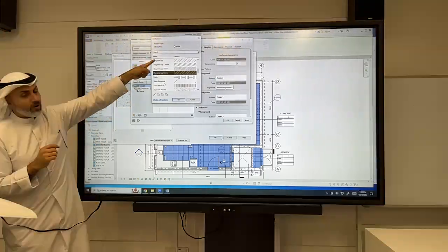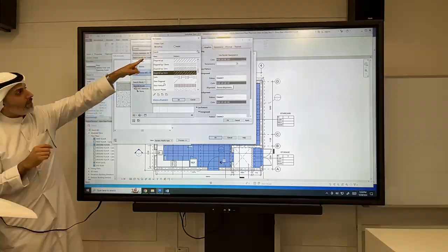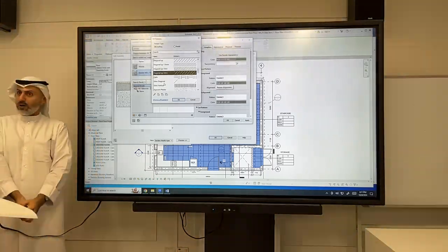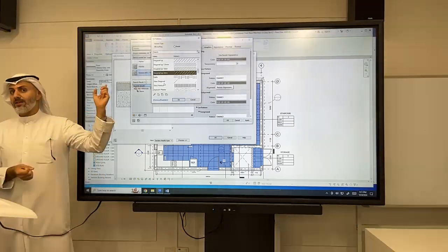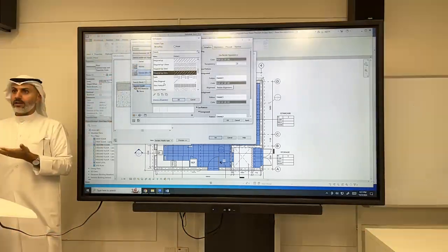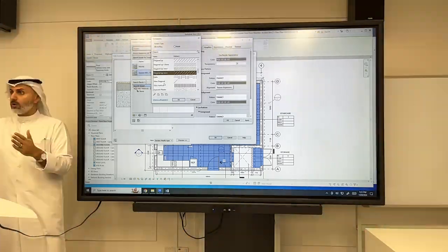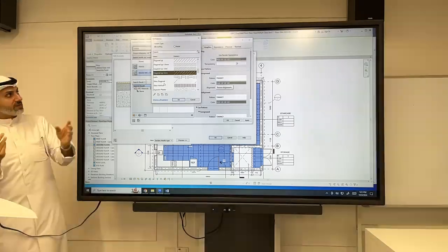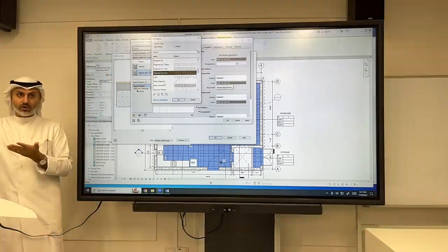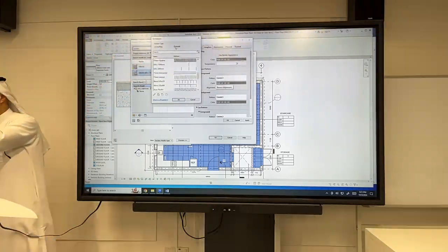Okay? Model is actual project scale. When I put model, for example 50 cm, if I zoom out, it's going to look smaller. With the drafting, it doesn't. So usually I use drafting when I cut patterns. Then when I zoom in, zoom out, I don't want the spacing to become wide when I'm zoomed out. I want it to show as 1 millimeter as well. But that's the difference. When we're showing a surface pattern, it's going to show in scale, plan, elevation, so we choose model. Okay, so surface pattern, model,